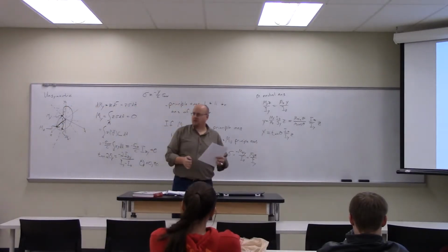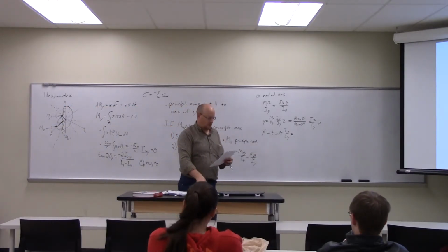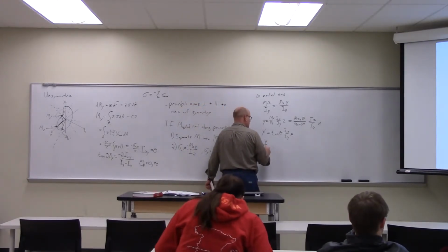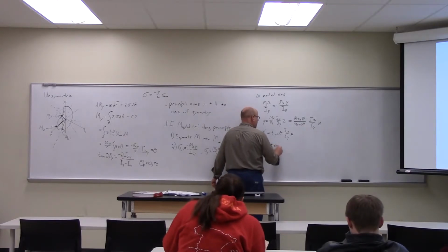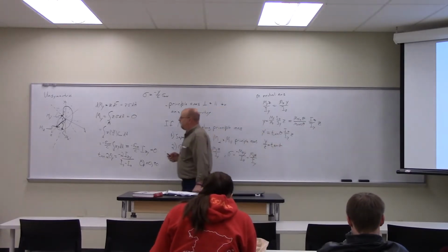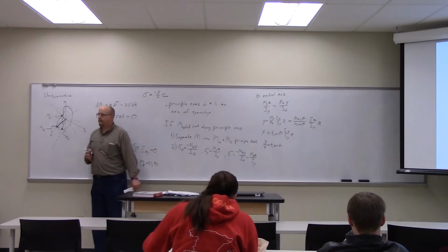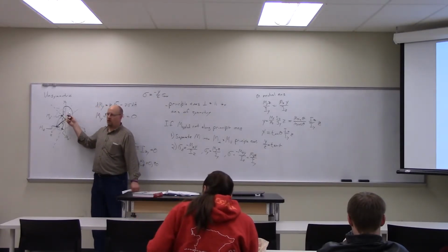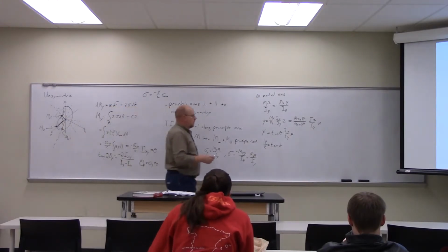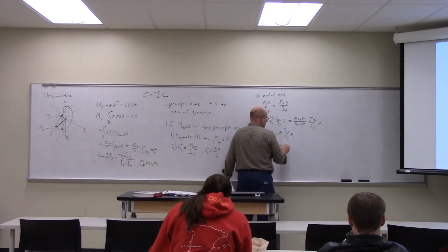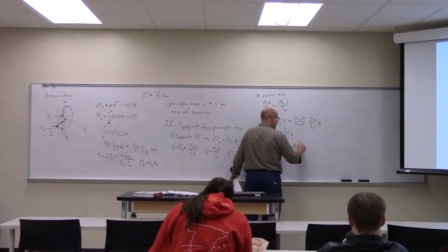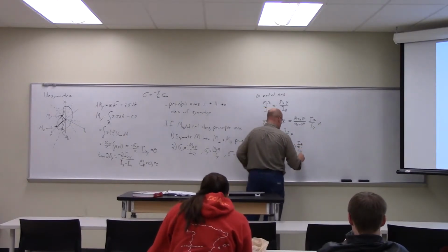Right, so the neutral axis is some angle alpha relative to the y-axis to begin with. So y over z is going to be equal to the tangent of alpha. Along any coordinate along that line, y over z equals the tangent of alpha. But according to my rule up here, that's going to be equal to the tangent of theta, Iz over Iy.